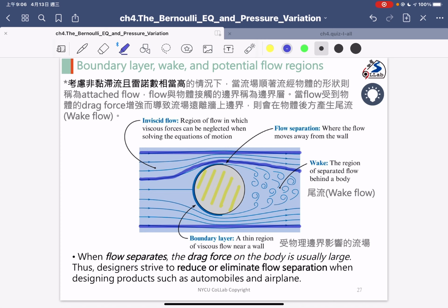And one of the very important streamlines, just horizontal, like the green line showing here. The point where the streamline contacts the object, the black point in here, we call the stagnation point, 停滞点. At this point, the velocity will equal 0. So the flow will stop in here.